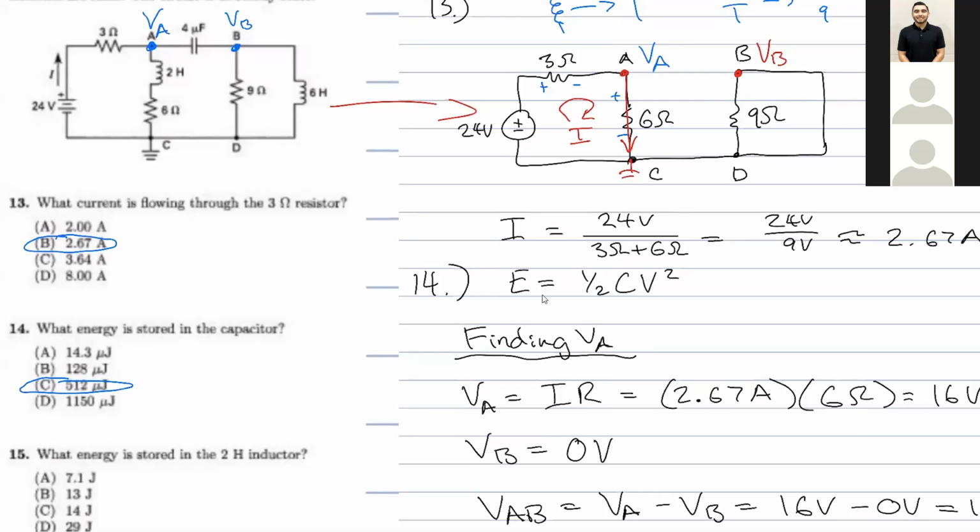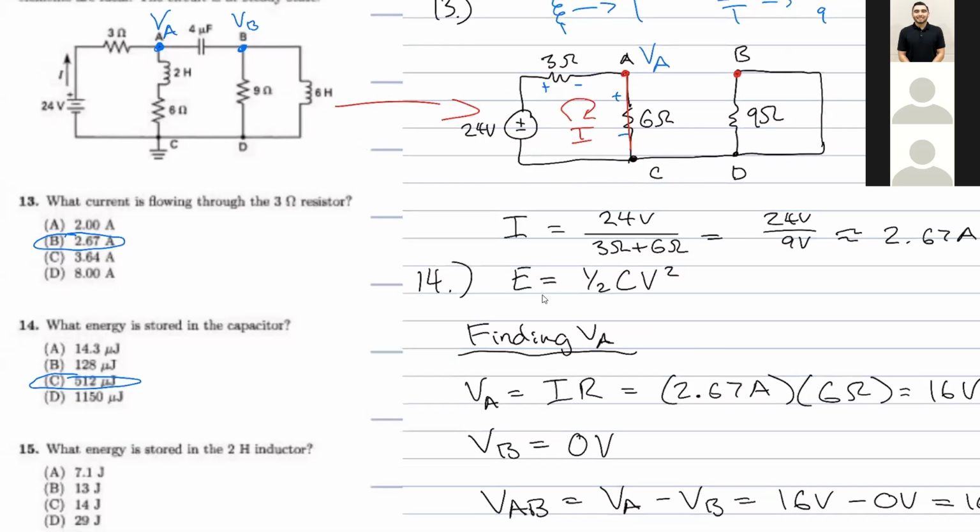And if this was ground right here, as it's stated in the diagram, that is going to be our reference. Whenever we're getting a node voltage, we always want to compare that point to the reference. And since our reference was 0 in that case, that's why we had to choose that resistor. You wouldn't go around and do it from that way. That wouldn't be the right way to do that. Okay, that makes sense. Thank you. Any other questions? No? Cool. All right.